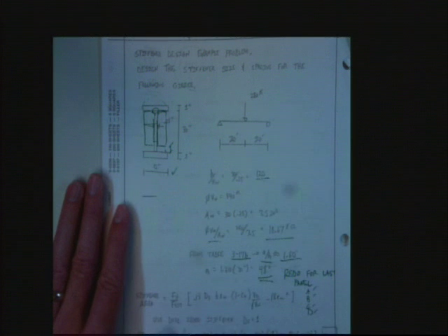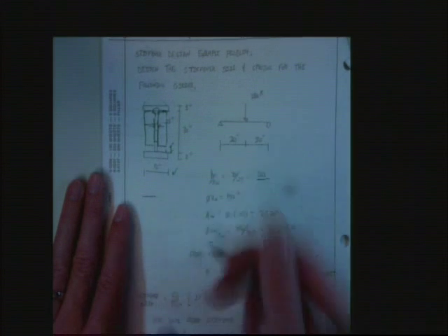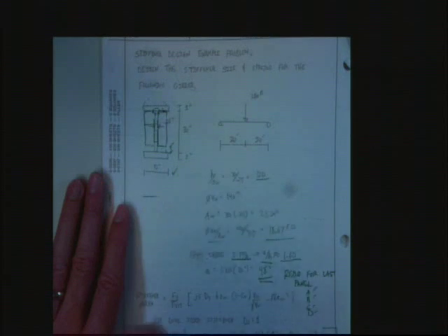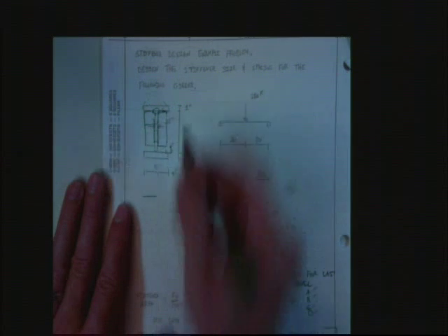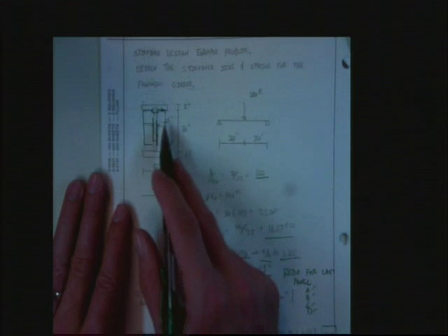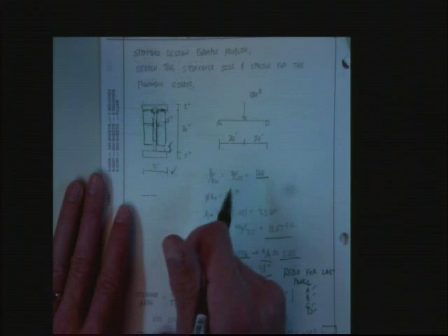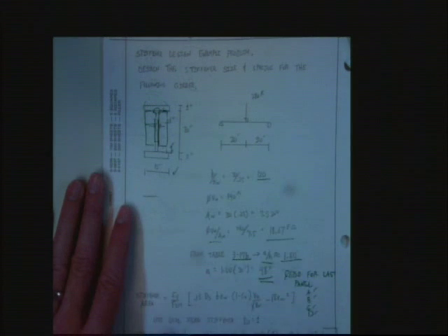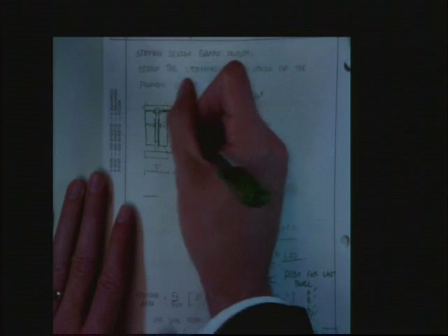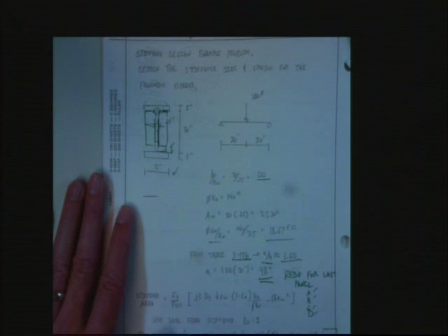I do not recommend welding all the way around on your stiffeners because your welds will fight one another. Sometimes you'll break one, and sometimes you'll cause imperfections or cracks in welds, because you'll make this weld first and this weld second, and maybe they'll cool differently and actually pull themselves apart. Does that make sense? So you always weld on your web. You pick a flange that you're going to be up against, and you weld on that. If you absolutely have to take it to the bottom, you make it flush, and I don't usually require them to weld.